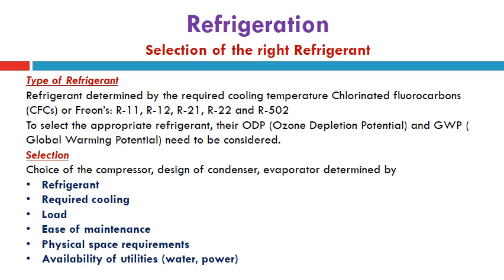Also, in water cooled systems, for the condenser, water must be provided with a certain amount, taking into consideration the costs of running water and the temperature increase between the supply cooling water temperature and return water temperature, that may require adding a cooling tower or using seawater or river water, some kind of raw water.